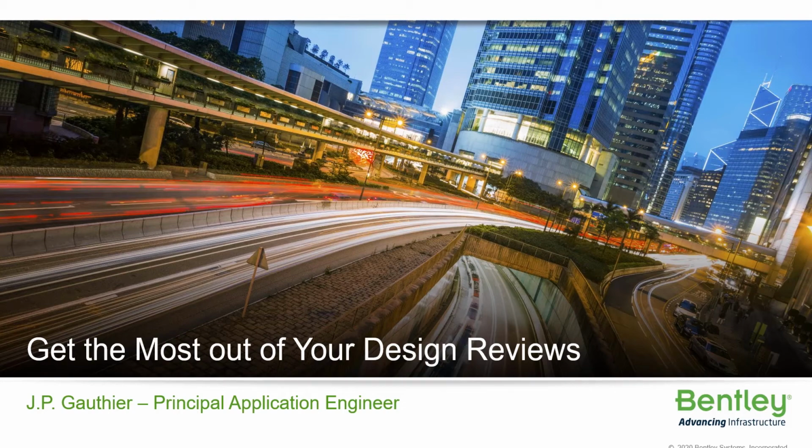I'm a Principal Application Engineer with Bentley Systems, and we're going to talk about getting the most out of your design review. This is going to be a session that will use our new iTwins technology inside of ProjectWise 365 to generate an iTwin and then be able to comment and provide issues and create markups inside of the iTwins design review viewer, and then be able to look at those issues inside of MicroStation or OpenRoads Designer applications, make some changes, and then circle back into the design review and close those issues, as well as then update the information all inside ProjectWise 365. So let's get started.